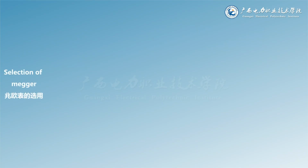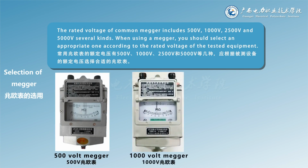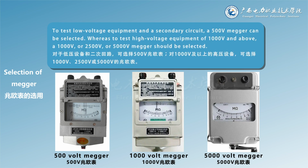Selection of Megger. The rated voltage of common Megger includes 500 volt, 1000 volt, 2500 volt and 5000 volt, several kinds. When using a Megger, you should select an appropriate one according to the rated voltage of the tested equipment. To test low-voltage equipment and a secondary circuit, a 500 volt Megger can be selected. Whereas to test high-voltage equipment of 1000 volt and above, a 1000 volt, or 2500 volt, or 5000 volt Megger